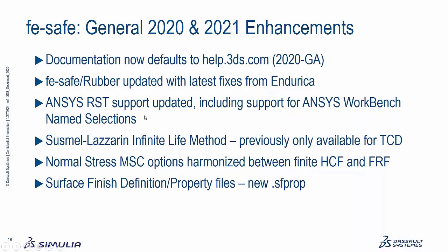As part of the TCD effort in the past, people had said that some of their life predictions had a lot of shear in them, and we needed to take some shear into effect. We couldn't just use the normal stress kind of algorithm. So we'd added the Susmel-Lazzarin infinite life method. It was only at the TCD location that you could use that method. And now we just made that available generally as another general algorithm.